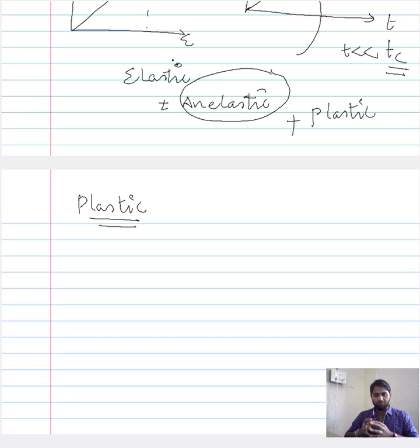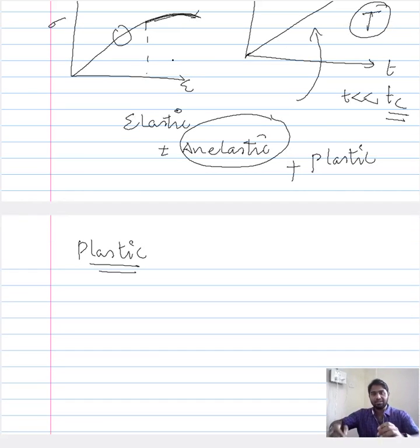Therefore, what we observe is that for the plastic deformation to continue, in the general stress strain case, you have to impose an additional amount of load. That is the reason for this typical manner of the curve: once the dislocation density continues to increase, you have to impose additional stress to ensure that the plastic deformation continues.